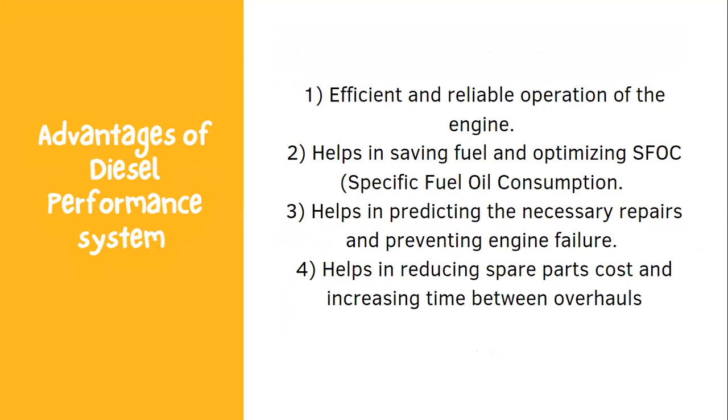Advantages of diesel performance system. First is efficient and reliable operation of the engine. Second, it helps in saving fuel and optimizing SFOC, or specific fuel oil consumption. Third, it helps in predicting the necessary repairs and preventing engine failure. Fourth, it helps in reducing spare parts cost and increasing time between overhauls.